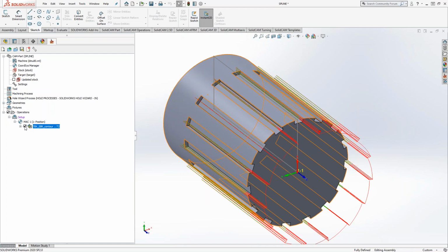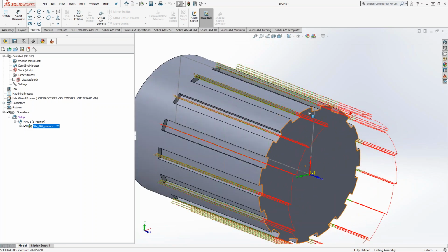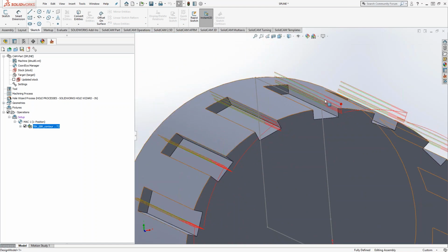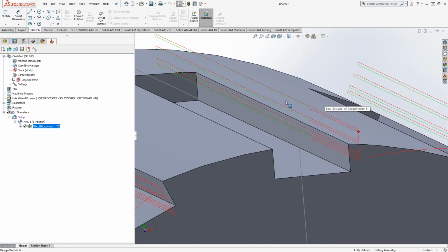It's going to look like that, and you can also see that I've added my fourth axis indexing to this as well. So my fourth axis transform is added to that. So not only am I broaching or making a keyway on the front there, on the top side, so there's my machining, my retraction, reposition to get my next cut.